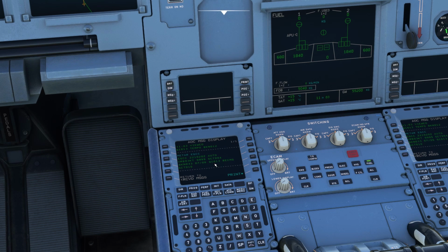Now what you can see is we've got the QNH, I believe the temperatures. One is the actual temperature of 7 and the other one is the dew point. We've got the wind speed here. We've not got the direction because it's saying it's variable. So VRB variable and 3 knots. Basically all that information that you needed should be there, minus maybe the transition altitude. The transition altitude won't be there, but you can easily find that or work that out yourself. Worst case, just guess. It's not too much of a problem.